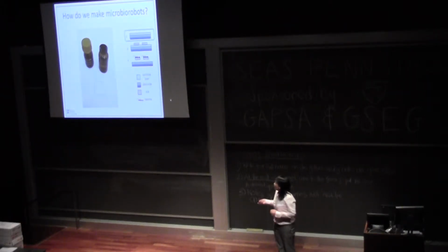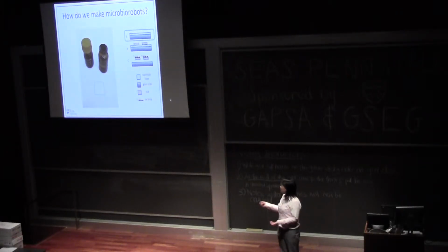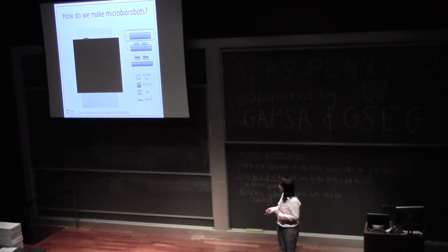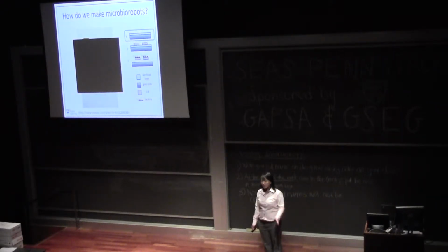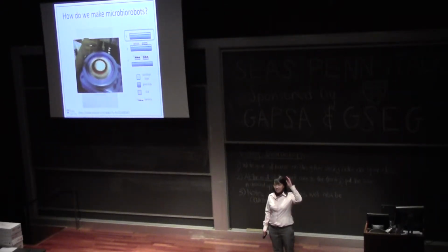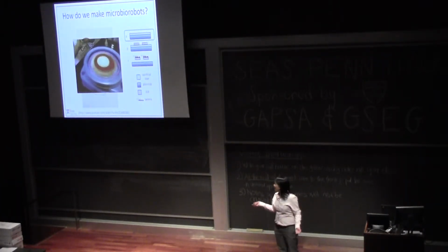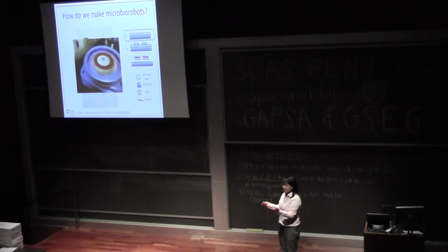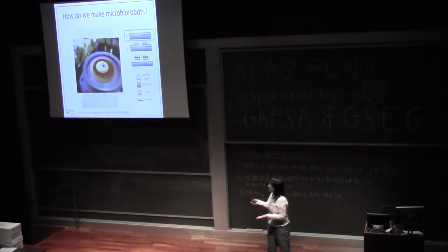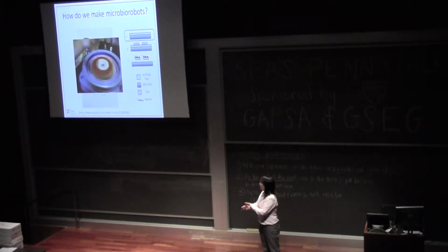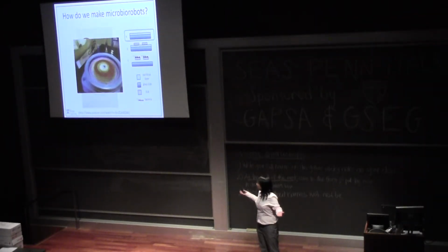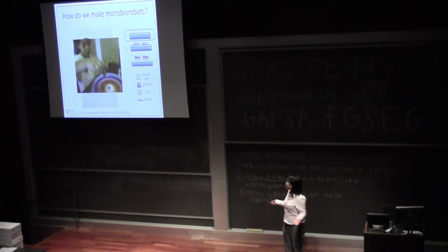So we start out, we make these microplates using a process called photolithography. Similar to the way that circuit boards are made, we start with these chemicals that we'll spin coat onto a glass slide. So just a show of hands, as a kid, how many of us tried spin art? The spin coating process is actually really similar to spin art. We're rotating the glass slide, and then we are depositing a layer of solution onto it, and because it's spinning, the centripetal forces pull the liquid, and we create a really uniform thin layer.